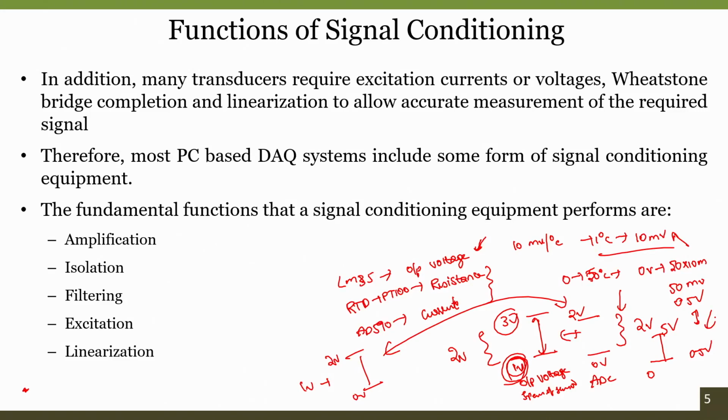And if you map it with respect to the range of your ADC, finally you can utilize the complete levels of an ADC, and the complete accuracy of the system will be improved with a lower bit ADC itself. So that is the role of signal conditioning circuits in most of the interfacing systems.